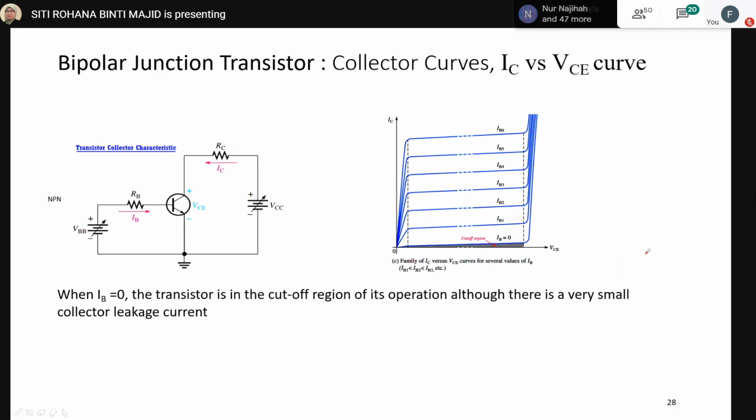So here is the IV curve of the BJT. In other words, this is the output characteristic of the transistor. You can see that we have a saturation region here, where there is a rapid increase of current when you change the voltage, and after this period, it is an almost flat region.